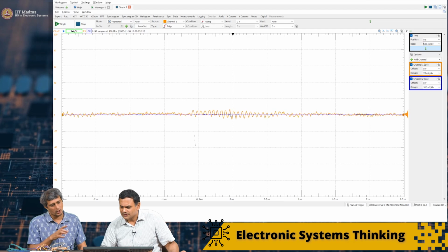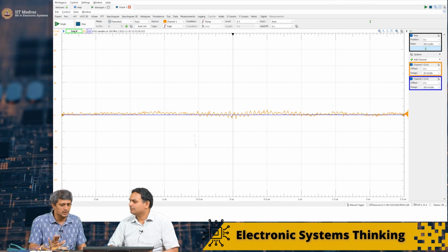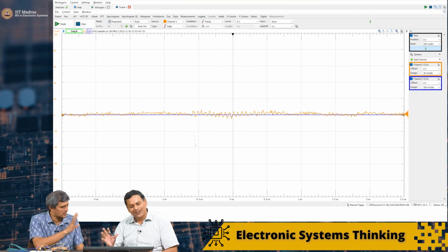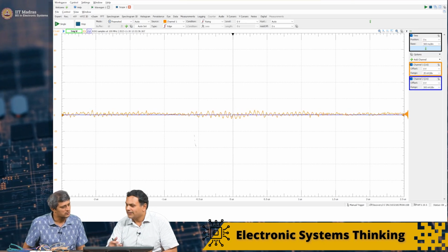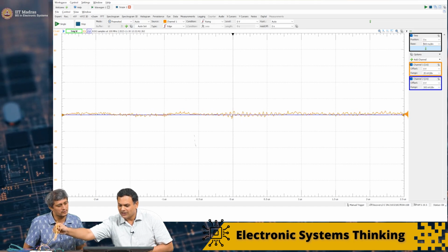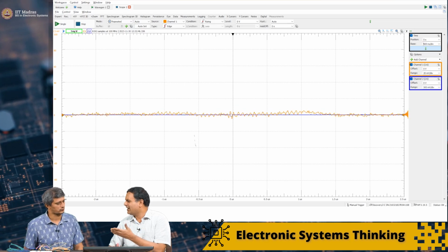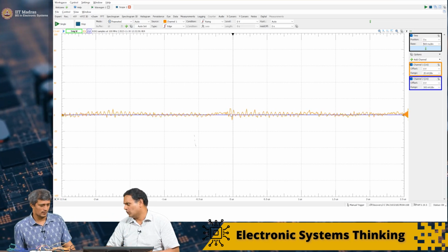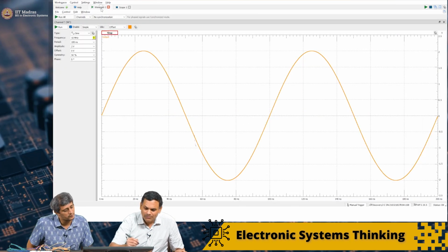So the point you're trying to make is that there is some background noise being picked up by this loop antenna at around 10 to 20 megahertz. We didn't make that calculation exactly. And it seems to be intermittent as well, going on and off. There are various things related to this. It could even be your body picking up some part of it, and the orientation matters and so on.